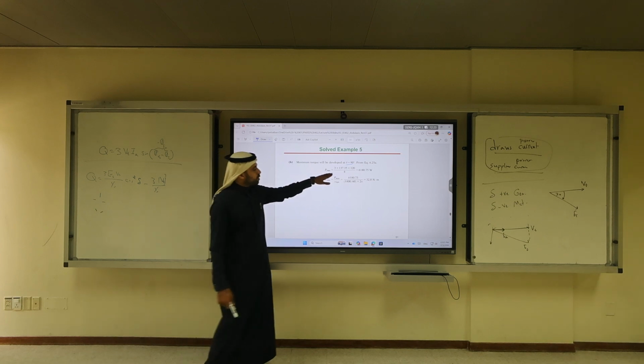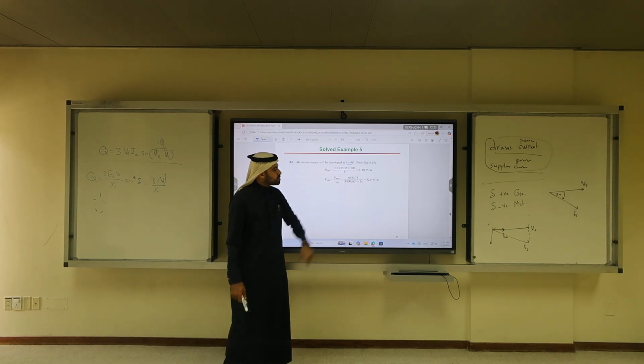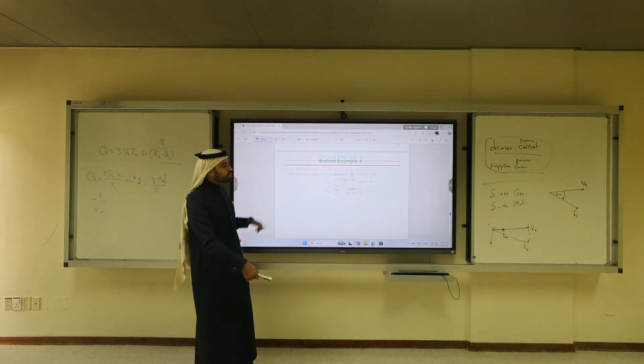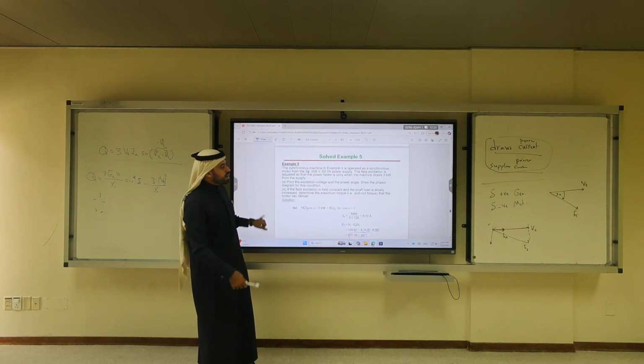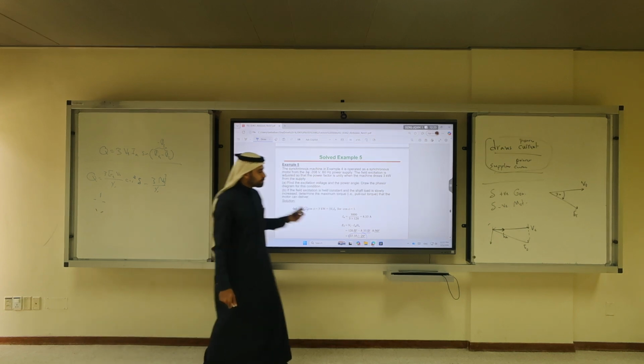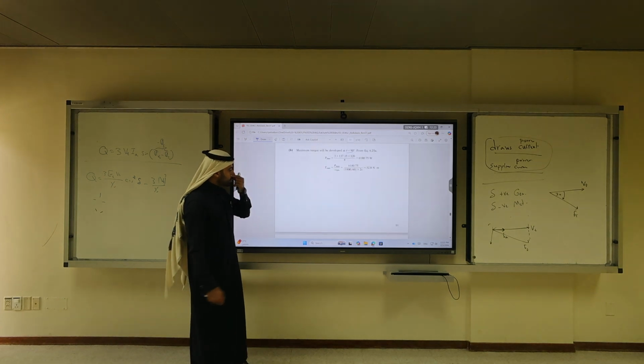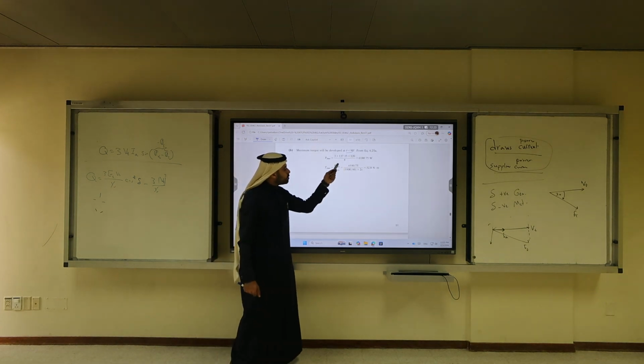So what's the maximum torque? 3 times Vt Ef over Xs, 6,000 watt. That's twice the usual rated or operated one. The operated one here is 3 kilowatt. So do not allow your electric motor to exceed that, and then you divide maximum power by the synchronous speed.